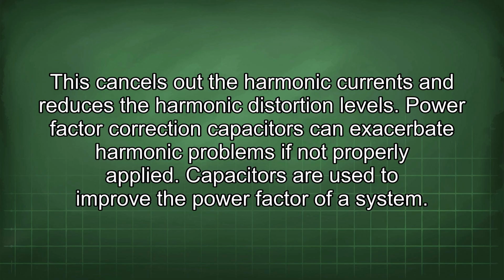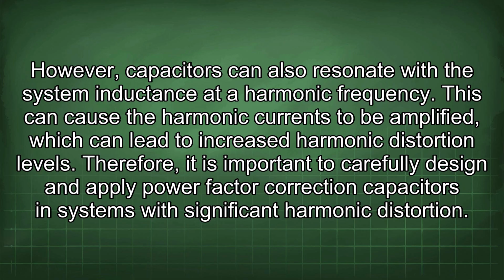Power factor correction capacitors can exacerbate harmonic problems if not properly applied. Capacitors are used to improve the power factor of a system. However, capacitors can also resonate with the system inductance at a harmonic frequency. This can cause the harmonic currents to be amplified, which can lead to increased harmonic distortion levels.